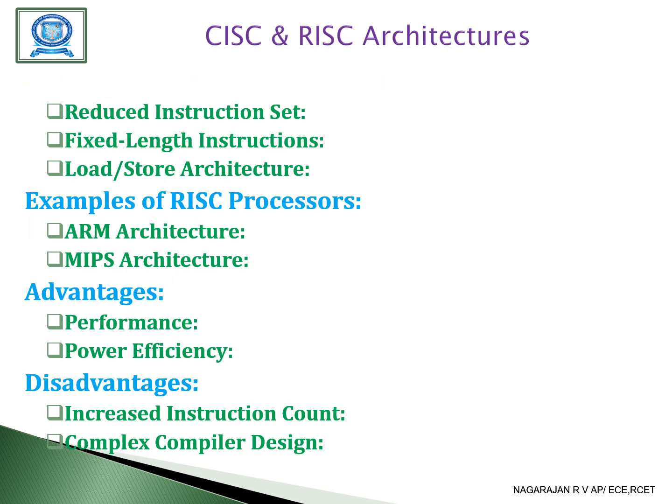Next, let us see the RISC architecture. Reduced instruction set. RISC processors are designed around a smaller, highly optimized set of instructions. It has a fixed length instruction, so RISC instructions are typically of a fixed length, which simplifies the fetch and decode stages of the CPU pipeline.